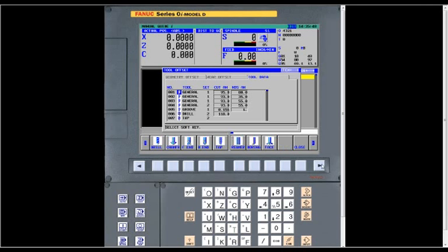That takes us to our next set of tools. These are on-center type tools for a lathe. You have a drill, a chamfer, a flat end mill, a ball nose end mill, a tap, a reamer, a boring bar, and a face mill. Then if we go right shift one more time, we have one other tool. This tool is like a turning tool that's like a grooving tool. You can groove and turn and face with it. So that's all of our different selections.